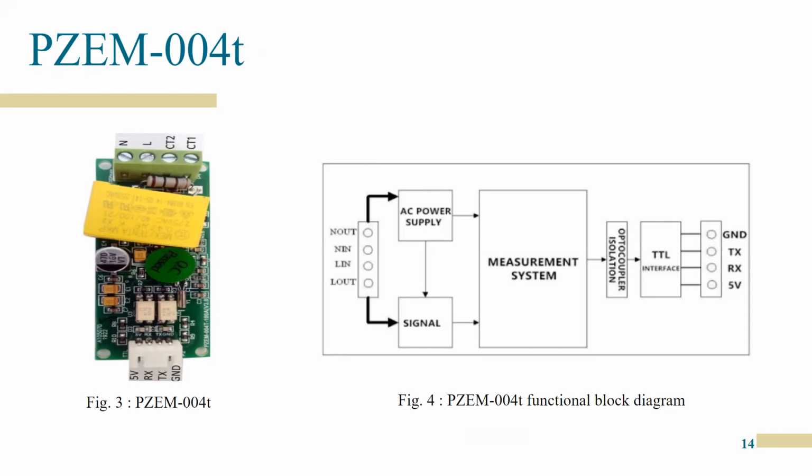If you want current or voltage, each will have a most significant byte, that is the higher order byte, and a lower order byte. They are stored in some locations, all of which are available in the data sheet, so we can have a look at the memory locations. And the task is that we have to process that data using code with the help of the NodeMCU. That is how the communication and processing will take place.